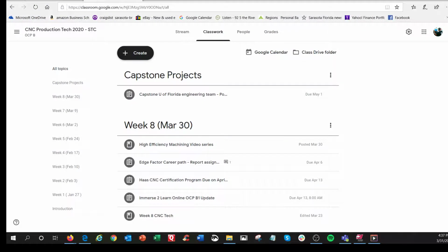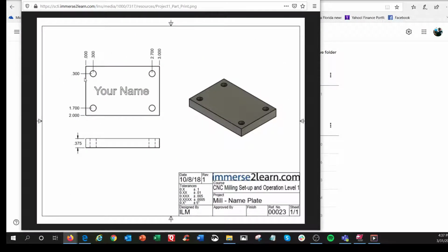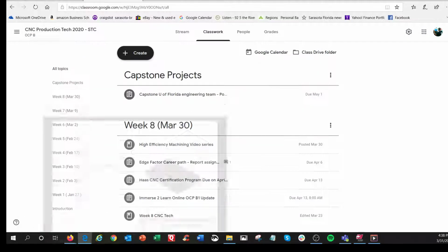So if we're looking at it from a CAD CAM point of view, let's go back to the print here. Where is our 0? I see it says 2 inches down here, so 0 in the Y direction is here, and the X direction. This is where you want to base all your coordinates on, whether programming by hand or by CAD CAM.